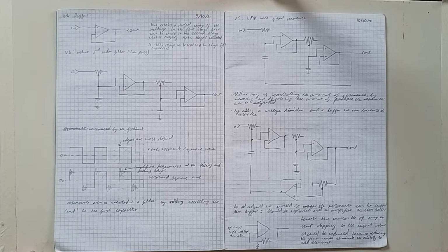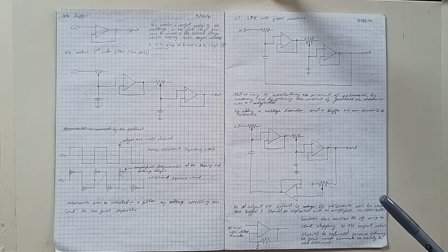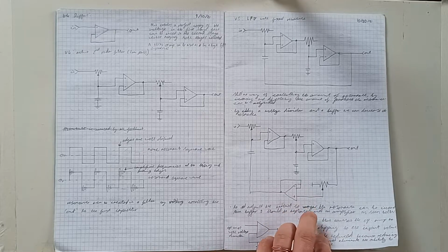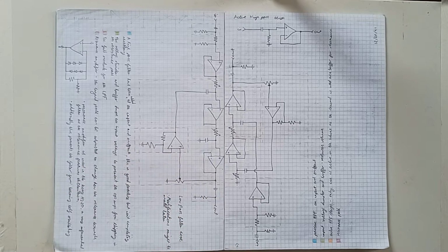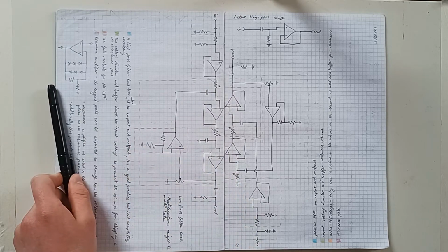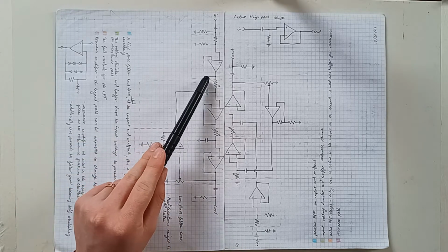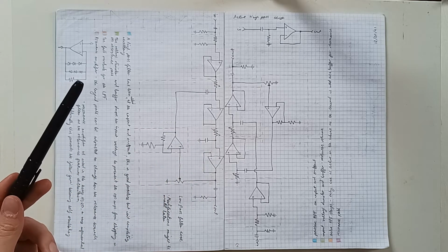In the previous video, I got as far as explaining up to a basic active cascade filter. In this next video, though, I would like to talk about different topologies of filters and how they work. So, as already mentioned, this is a cascade filter. The one on this half of the page is set up as a low-pass filter, which, if you remember, has the input signal going through a resistor with a capacitor going to ground.